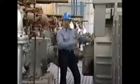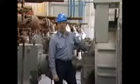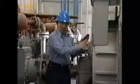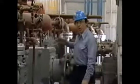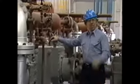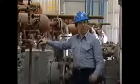The drive unit of the compressor supplies the power for compression. Rotary motion from the power source is converted to reciprocating motion by the crankshaft, connecting rod, and crosshead. Let's take a moment and look a little closer at how each of these parts functions.